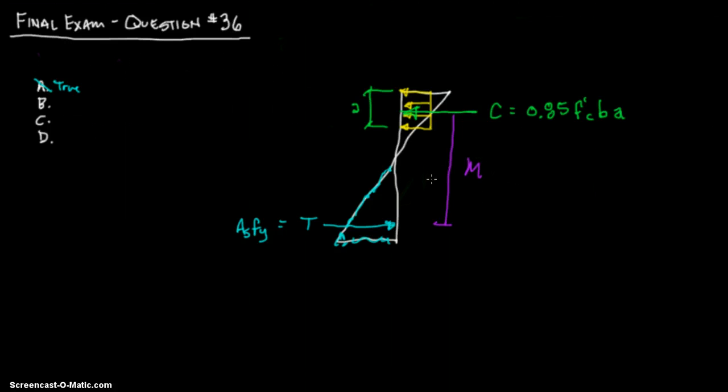All right, and here's your neutral axis. Let's call it NA. And that moves up and down depending on how much steel you have. If you have more steel, it will push this compression block down because you have more steel to stress, and it means more of the compression concrete can be engaged.